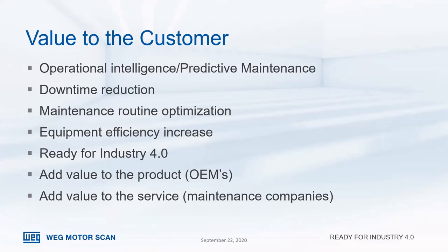There's 3 main things that are really critical when it comes to a motor application. One is sizing it appropriately for the application, which you could spend a whole day discussing, how to do it, and all the different applications, which we're not going to do today. The second one is the environment that the motor is going to be installed in. You've got to make sure that mechanically it's designed to work within the environment that it's going to be installed. Like I mentioned before, you've got a paper mill, which can be a very nasty application. Steel mills, that's a very nasty, dirty application. You have to make sure the enclosure is able to handle that.